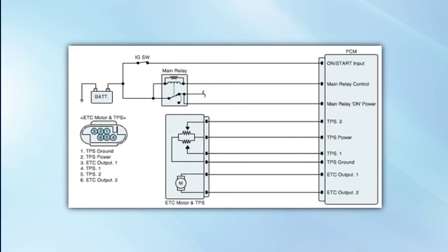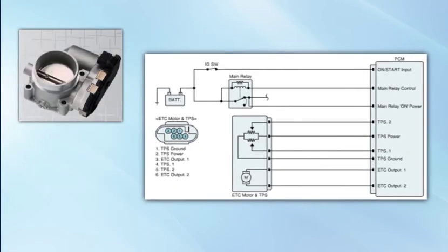Many sensors, such as an ECT sensor, provide resistance to current flow. Some components, such as a motor, have long lengths of wire in the form of a coil. A break in a wire or excessive corrosion can cause excessive resistance or an open circuit.